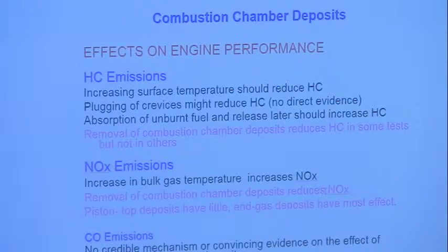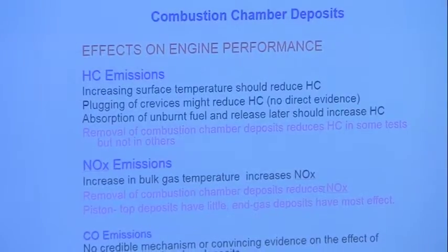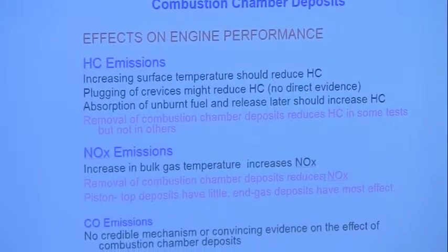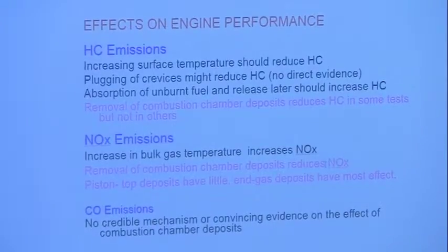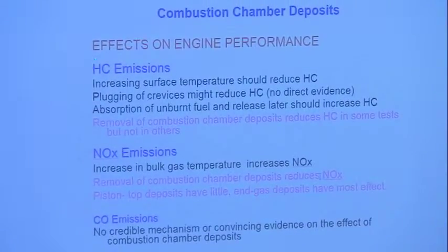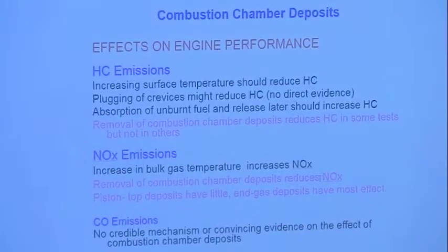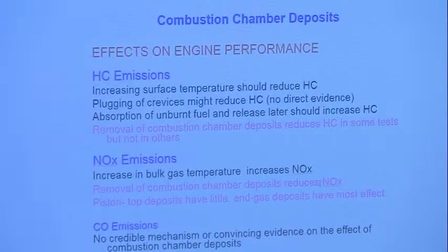In terms of engine performance, as I said, they have an effect on HC emissions. Increasing surface temperature should reduce hydrocarbons, and plugging of crevices by deposits must also reduce hydrocarbons, though there is not much direct evidence for this. It is just speculation. But absorption of unburned fuel and release later could increase hydrocarbon emissions. So there are several competing mechanisms which can affect this, and so the result is not very clear.